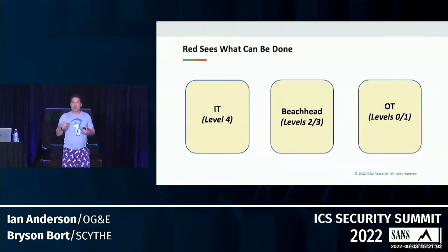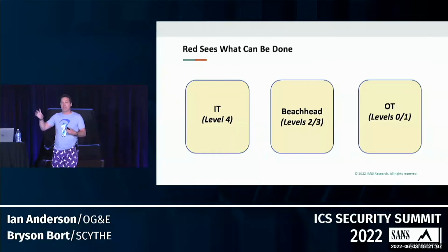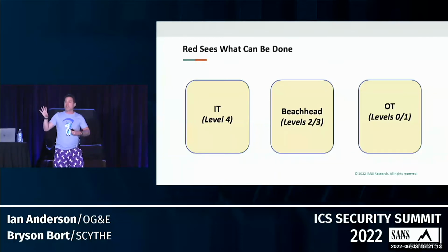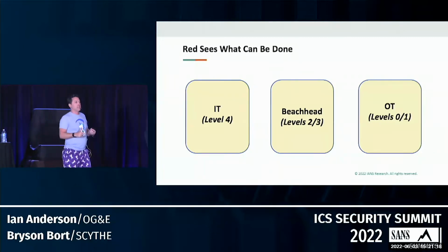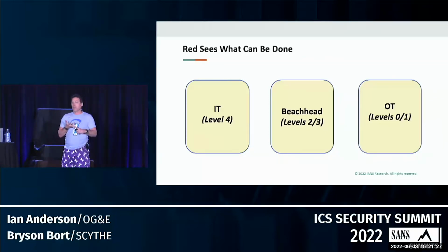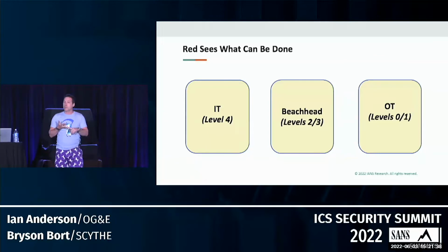Your IT is always connected somewhere to your OT environment. And that initial piece is right in the Purdue architecture, right? That's that part that we want to be DMZ'd for this. But here's the thing. Those are beachhead systems. Those are HMIs, those are DCSs, those are high-level systems that are there to manage, to monitor, and also to instruct. And what operating systems do they run? Pretty much very similar operating systems, typically 2 generations old and not patched, from what you have in your enterprise IT environment. Think about that. So how I got there is also how I'm going to get in.